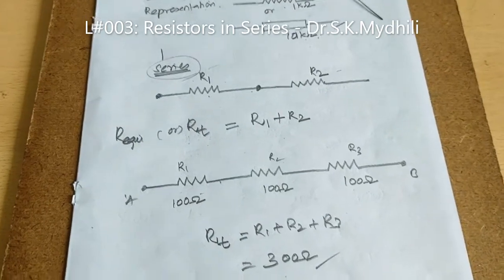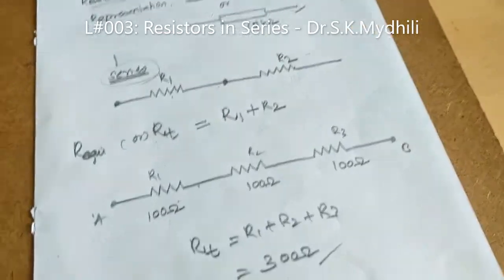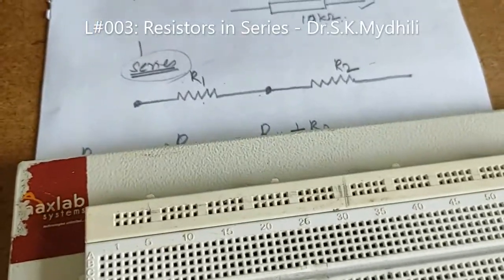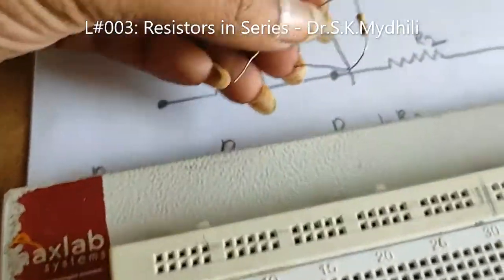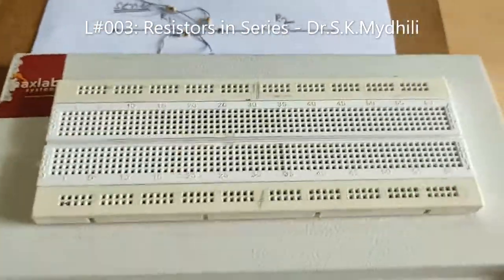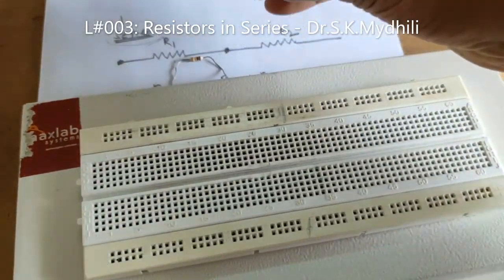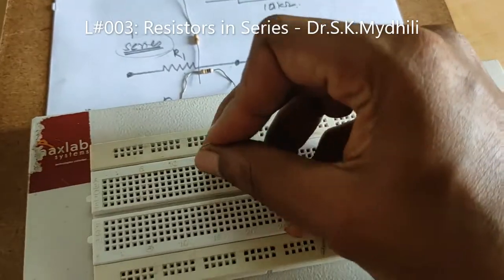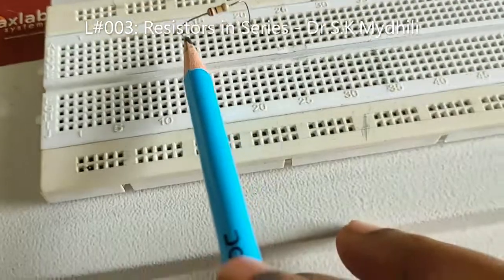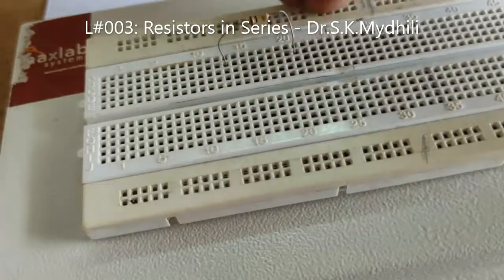So let me clarify how it is represented and how it is connected in terms of breadboard. Okay, so let me take a breadboard here and take three resistances. So I am taking three resistances. Okay, so I am going to connect them in series. So let me show you how it is connected in series now. So take one end and connect like this. So here I have used this and this terminology. Again, a series means you should connect like this.